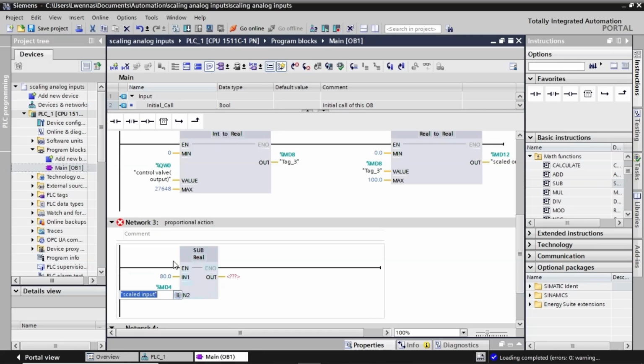It's noteworthy to mention that this program does not stand for a solution to the process, since in such processes we often use a PID regulator. However, today's lesson focuses on the practical use of analog inputs and outputs. Moreover, it also shows how to use math functions in a practical way rather than dedicating a whole lesson, which would seem tedious. Beware again, the choice of the process gain depends on the desired process response. In our example we start with 1, then you can test other values by yourself to see the difference.